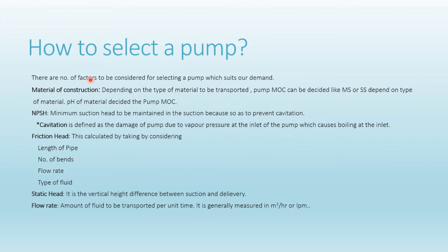There are a number of factors to be considered for selecting a pump which suits our demand. Material of construction is defined as the material of construction of the internal working mechanism, the pump outside casing, everything. Depending upon the type of material to be transferred, the pump MOC can be decided, like MS or SS.